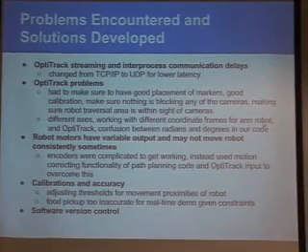And in our demo, we're not going to have the robot arm actually physically pick up anything. It will do the motion because all the inaccuracies in each component of our system will add up. So then the arm will not reliably always go into the right position. It will probably go in the general vicinity. It will be off by a few centimeters, but the accuracy was not enough given our constraints and our implementation. And a huge problem was software version control, Dropbox isn't the best.